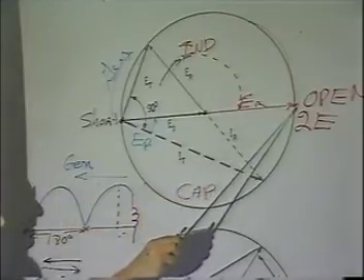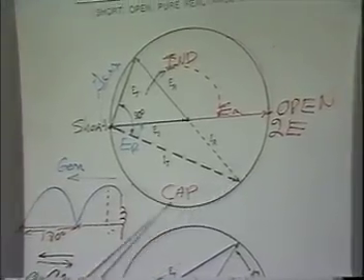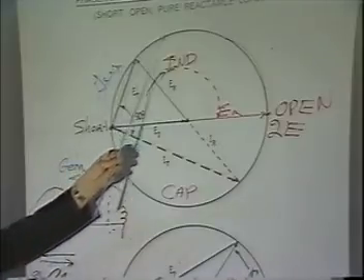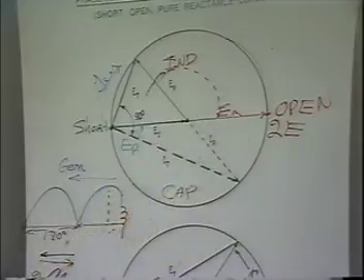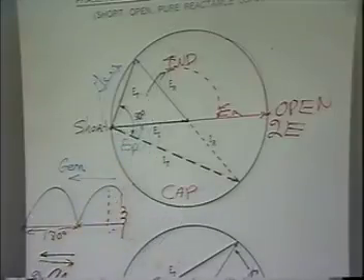When you come down here, all the way around here, the reflected voltage is total. Therefore, it's a pure reactive circuit. This is pure inductance here. If I told you that this circle represented resistance, then what value of the resistance would it have? Pure logic. If this is total inductance, this is total capacitance, what is the resistance?